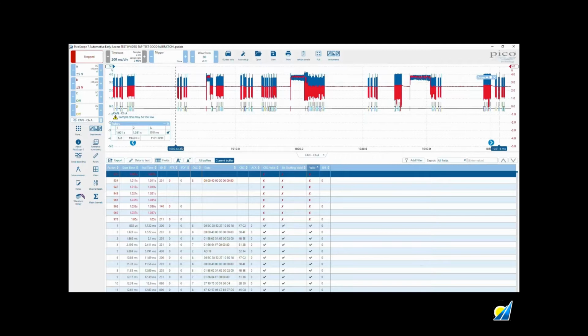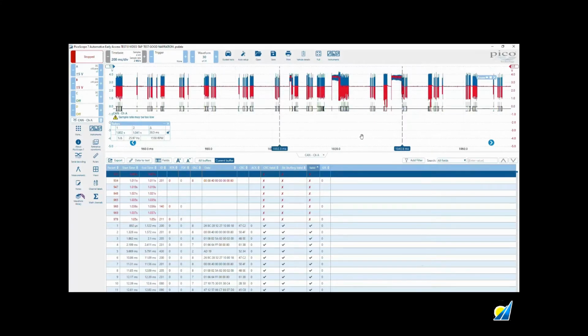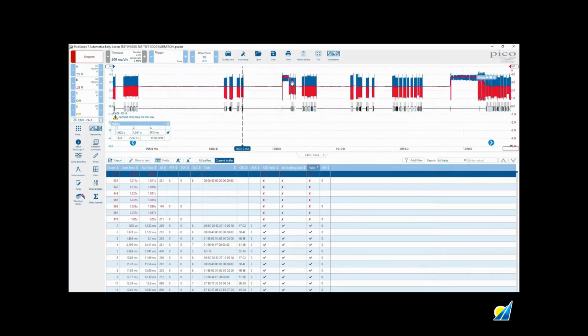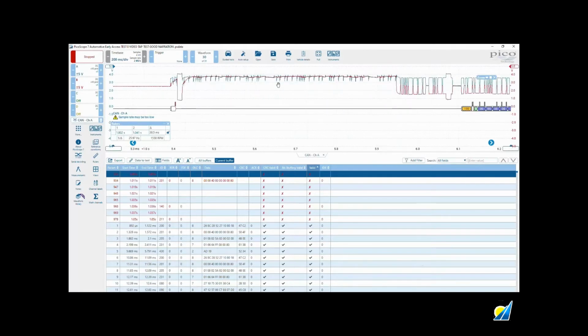And if we look at the time span of these, so that was our last valid transmission, and then we've got 1, 2, 3 events, and then we start decoding properly probably round about there. So we are there at 38 milliseconds. So within that 38 milliseconds, you can see that the CAN bus was driven high 3 times. Let's just zoom in on one incident. There it is.